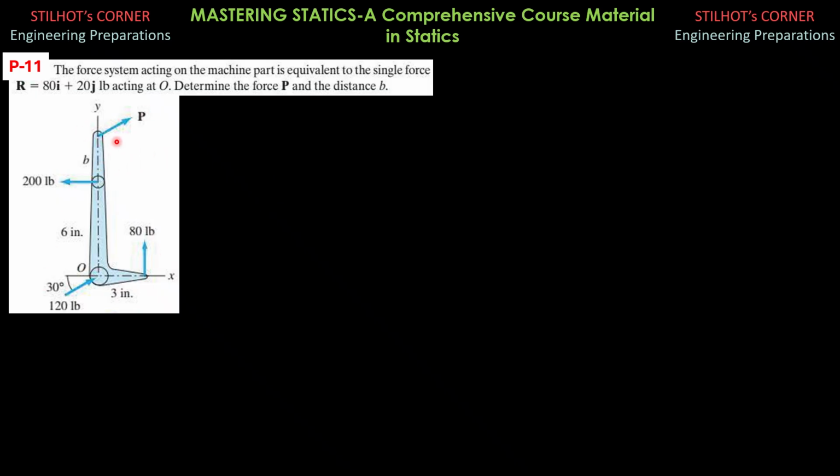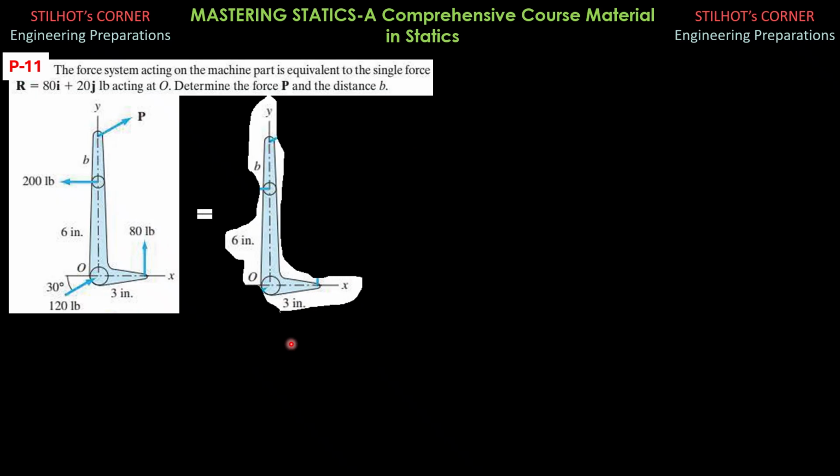So we have the x component, Px. The y component has no moment about O, so just Px and it is clockwise. So this is equivalent to the system with the force acting at O as shown with these values. That means the moment about O is 0 because the resultant acts at O.